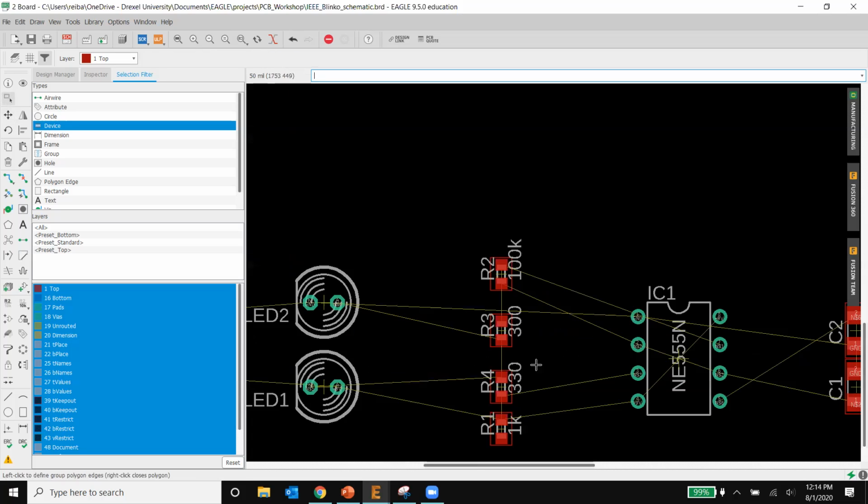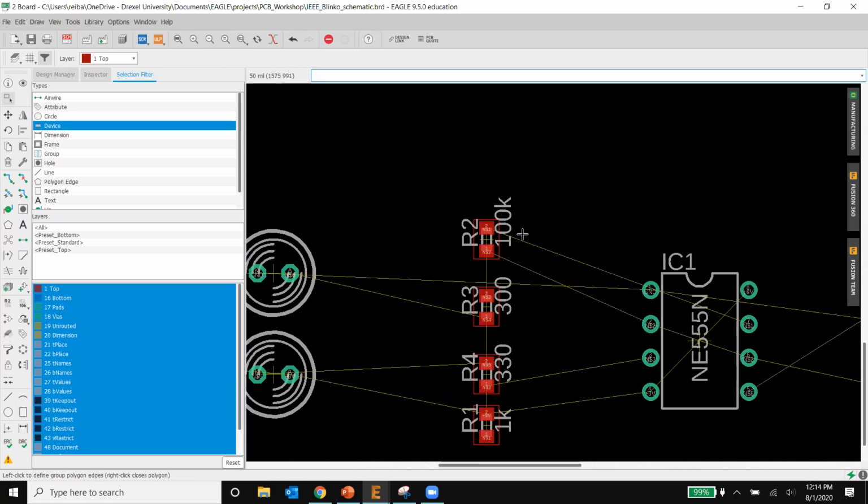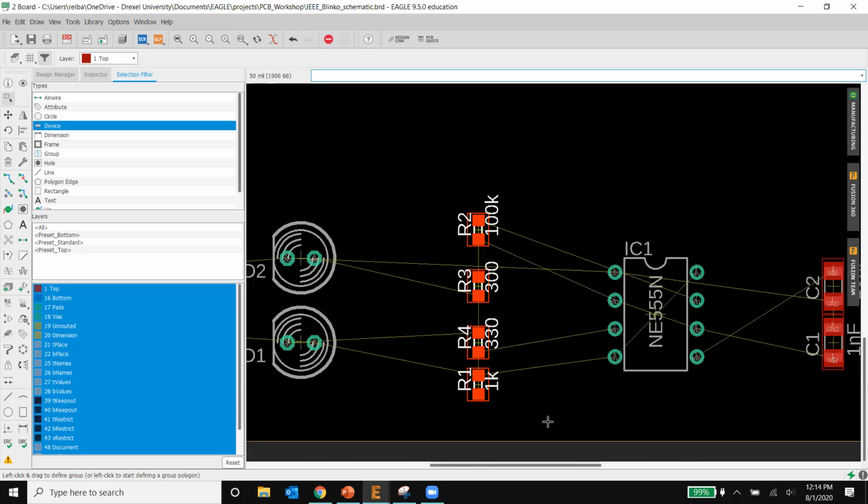Now if you notice, these things are not aligned here. They have different spacing from one another, and when you want to solder afterwards, you're going to have a bit of trouble. These are also surface mounted pads, so they're tedious already. So why make it tedious for yourself? If you grab all these and click here, you have this align option. So what you want to do first is align left edges, and then at the end of this toolbar, you have something called distribute vertically.